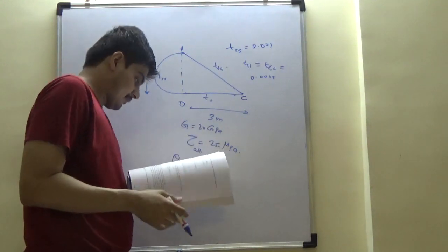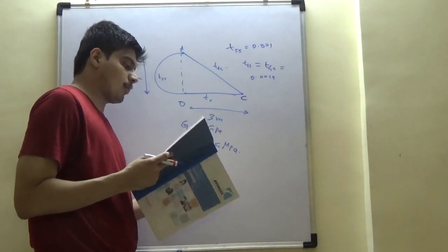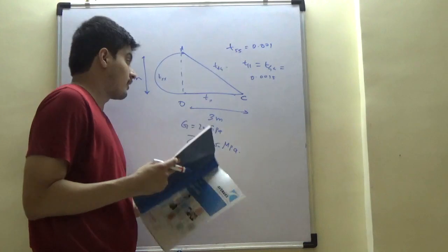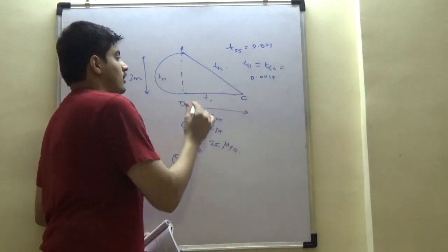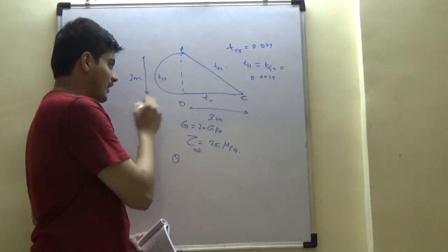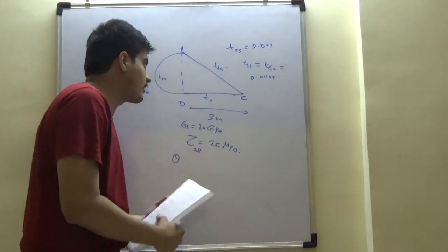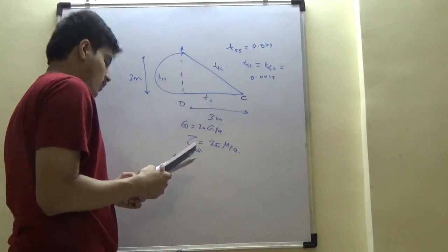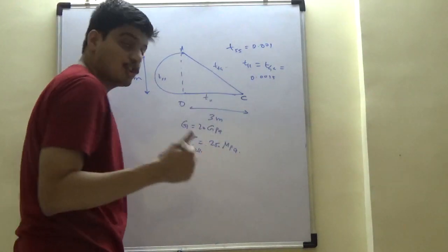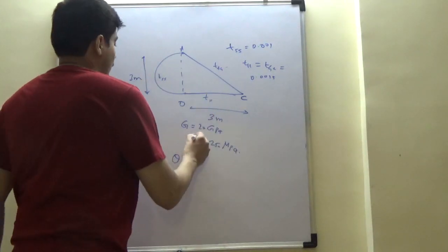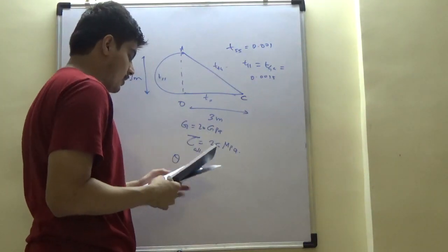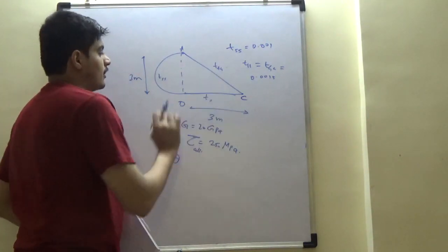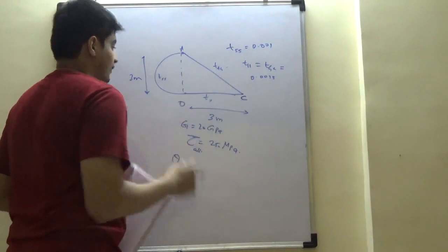This is an extremely important result, by the way. This is a cross section, the sectional view, right? Now rather than becoming an ellipse or a circle, it is this open-ended section with these thicknesses. So we have to find out the shear flows, and based on the shear flows we have to substitute these taus. So first we have to find the area.